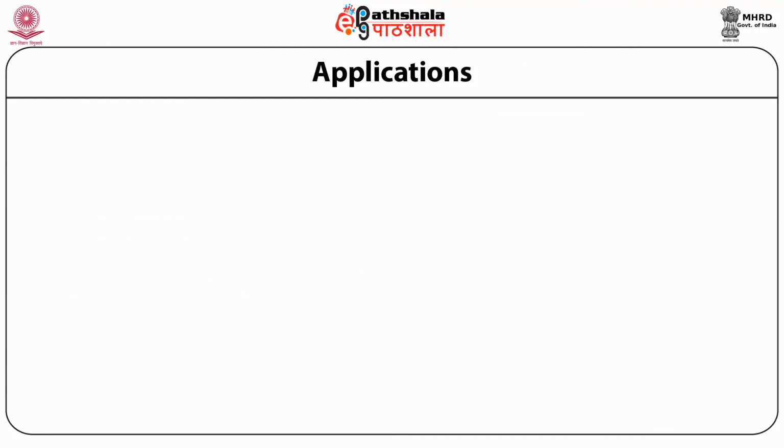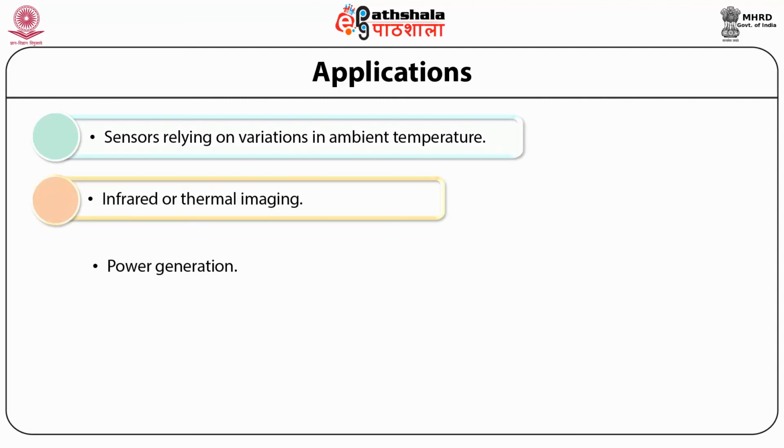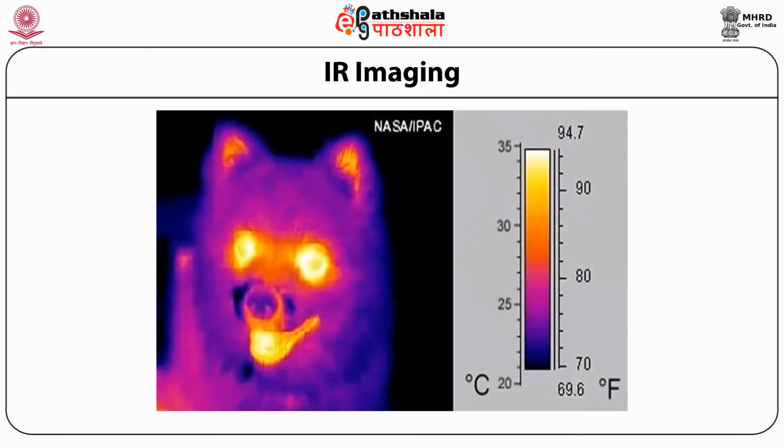Applications of pyroelectric materials. Some of the applications are in sensors relying on variations in ambient temperature, infrared or thermal imaging, power generation, burglar alarms, pollutant controls, and so on. Let us take one example, that is IR imaging. Just like we use visible light to make a photograph, infrared, that is IR radiation emitted by objects at different temperatures, is focused onto a sensitive plate to create a thermal image of the object.